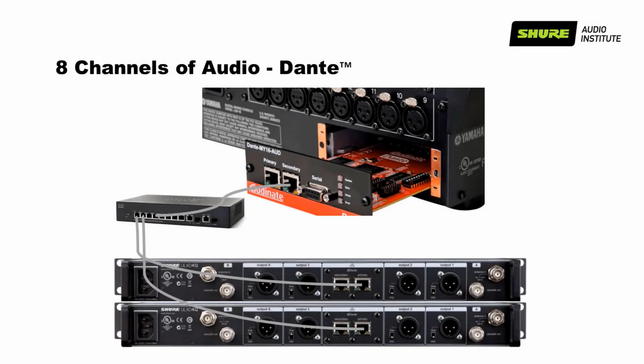You can often do it more easily by using off-the-shelf Ethernet hardware if you have a standard audio over IP protocol. Dante is an example of one. That's a protocol that Shure and many other pro audio manufacturers have adopted now, that allows you to put your audio signal onto an IT network. So in this case we've just got a standard switch, and you've got an Ethernet cable running from the Ethernet jacks on each one of these receivers to the switch. You connect your audio mixer to the switch, and voila, 8 channels of audio all running on essentially just an Ethernet network.